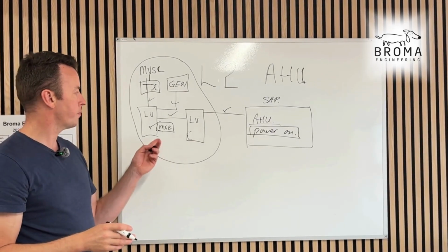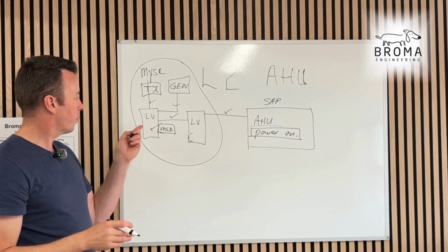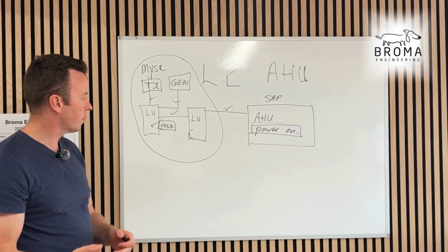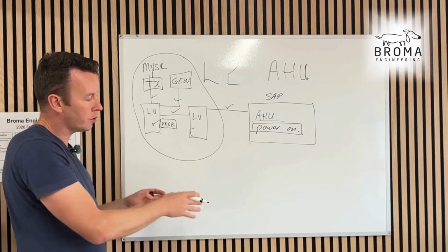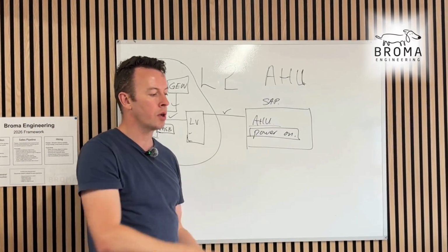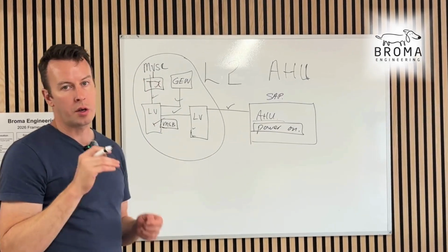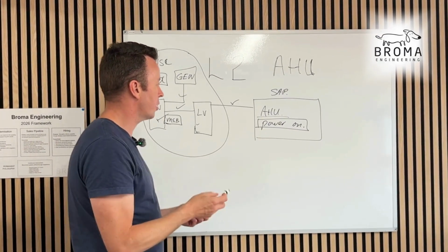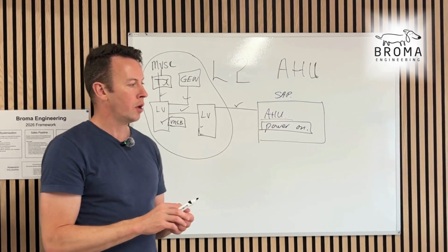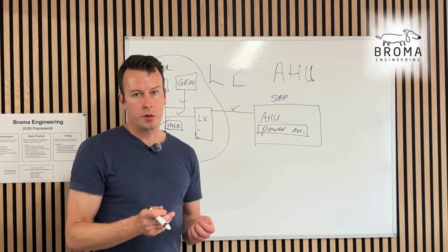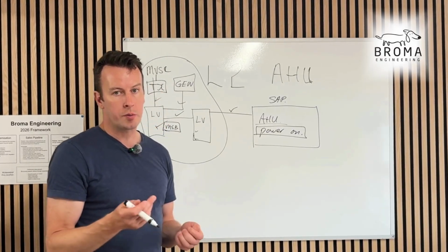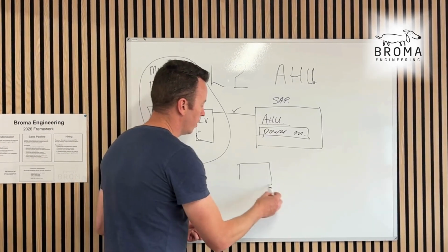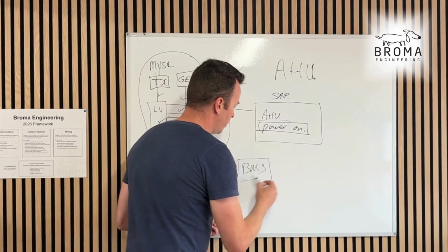This is where delays happen. So on the schedule, there has to be a cascading system. Power is cascading from an MV switchgear to the transformer into the main switchboard, down to your house mechanical distribution and into your AHU. Same with BMS, that the BMS cables are working, that the pre-power on is done. They have LV supply. Where is the supply coming from? You need to know what needs to be livened up upstream of the BMS. So you need to know this and learn it.